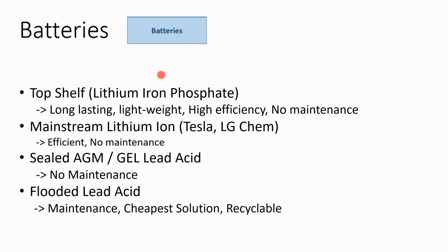You might have the same thing in the solar industry where you have a battery on site and the battery's role is not to provide backup power during a grid failure. The battery's role might just be to start the solar array during a grid failure during the day. And so, while it may not be appealing to a customer to hear during a blackout, you're going to have power during the day and you're not going to have any power at night.